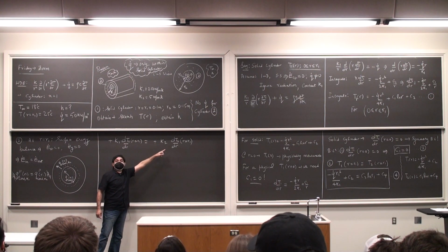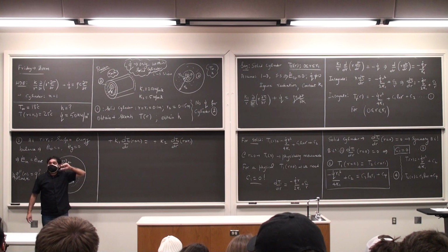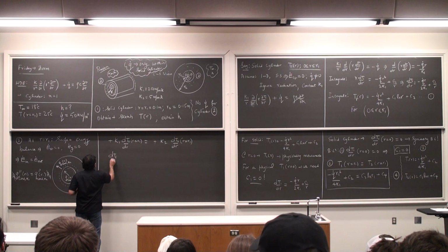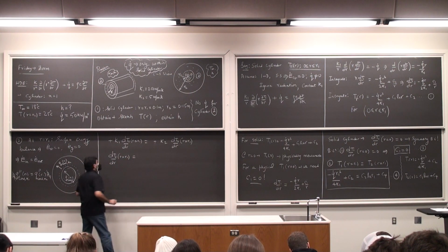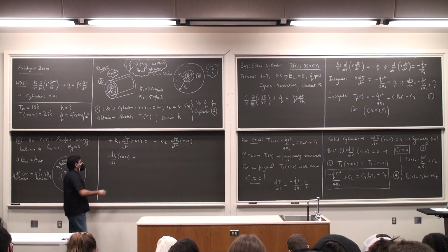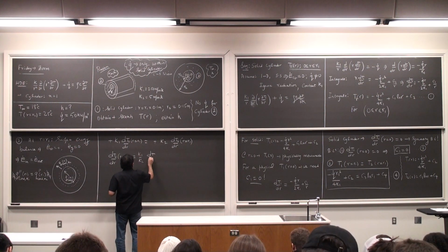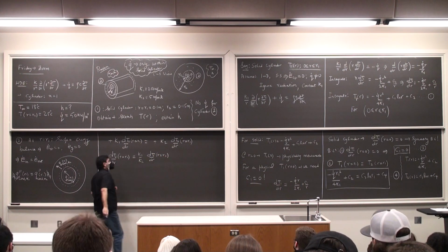This is the slope at R equals R1 as I enter the material of thermal conductivity K2. You will see the discontinuity here. dT2 by dr at R equals R1 is K1 by K2 times dT1 by dr at R equals R1.